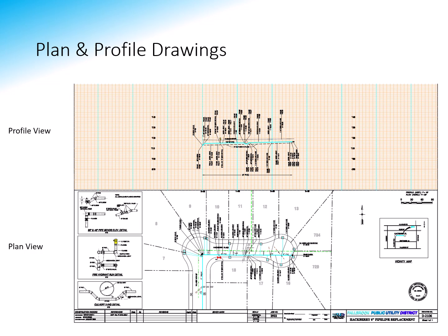So on your as-built drawings or your plan drawing, you're going to have two sets of plan views, I guess. You're going to have a plan and profile, right? So plan is just looking down on top of it. It kind of makes more sense when you're looking at it that way. Your profile would be if you cut away the earth and we're able to look at your facility from the side. So if you look at this example here, you've got the same information on both of these. It's just a different view.